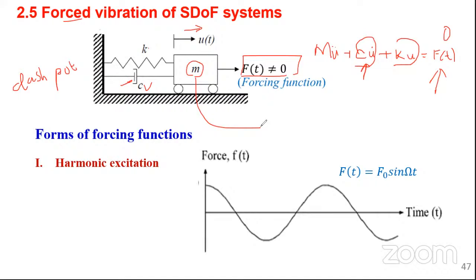So I find the D'Alembert's principle statement to be kind of restating what you already studied in Newton's second law of motion, F equals ma. Whatever he's saying is that to set this system in a state of dynamic equilibrium, you apply a kind of fictitious external force. Because of this mass and this direction, we are going to have inertial force, F equals ma.